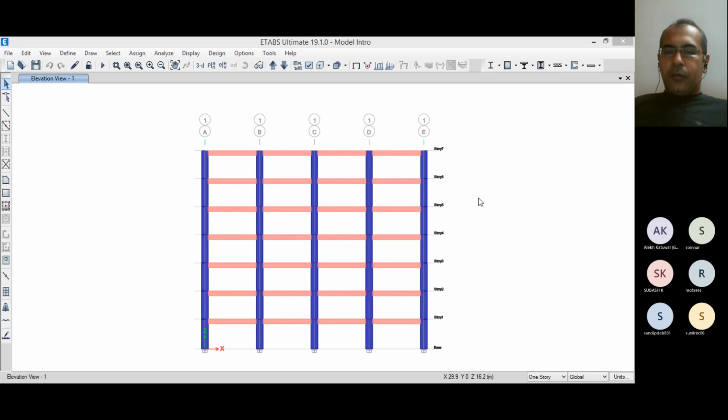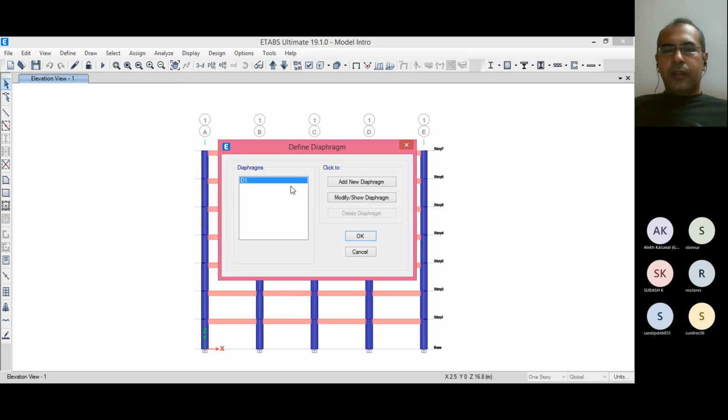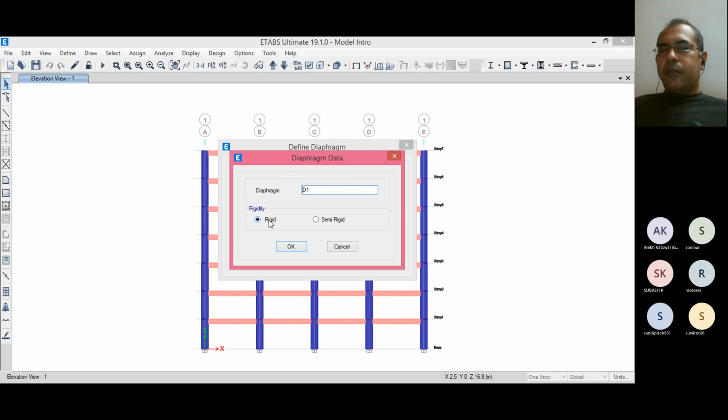Okay, so now once that is done, in lump mass model, the mass at the story level is rigid. Okay, so we call it a rigid diaphragm. So we assign a rigid diaphragm. We had seen in definition that rigid diaphragm can be assigned. Okay, so now if diaphragm is rigid, that means we can do a lump mass modeling. Okay, so your building can move only in one direction. So your analysis becomes simple and you can manually solve the problem. If it is semi-rigid, you cannot solve the problem manually. You have to depend on software. So to solve it manually we consider diaphragm to be rigid.